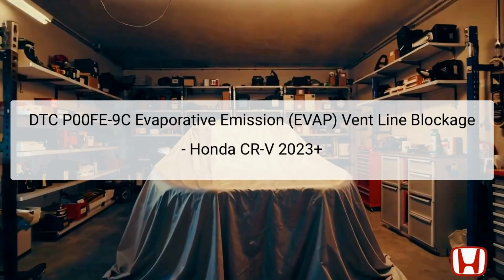The DTC code P00FE-9C indicates a blockage in the evaporative emission (EVAP) vent line. This problem occurs when the engine control module (ECM) detects an abnormality in the EVAP system's pressure. The purpose of the EVAP system is to capture and contain fuel vapors from the fuel tank, preventing them from